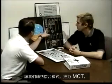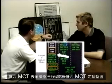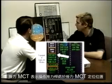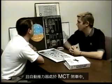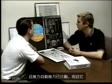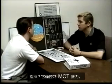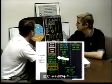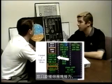Let's move down to the engagement modes. THRUST MCT. THRUST MCT means that the operative thrust lever is in the MCT detent, and the auto thrust is engaged. And it's commanding? It's commanding MCT thrust only. What about THRUST CLIMB? THRUST CLIMB means that the most forward thrust lever is in the climb detent, and the auto thrust is engaged. You get climb thrust only.